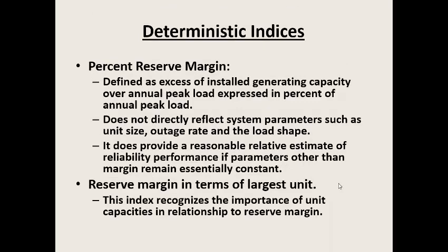Among the deterministic indices which have been used, one is the percentage reserve margin. The percent reserve margin is defined as the installed capacity minus the annual peak load, divided by the annual peak load and multiplied by 100.